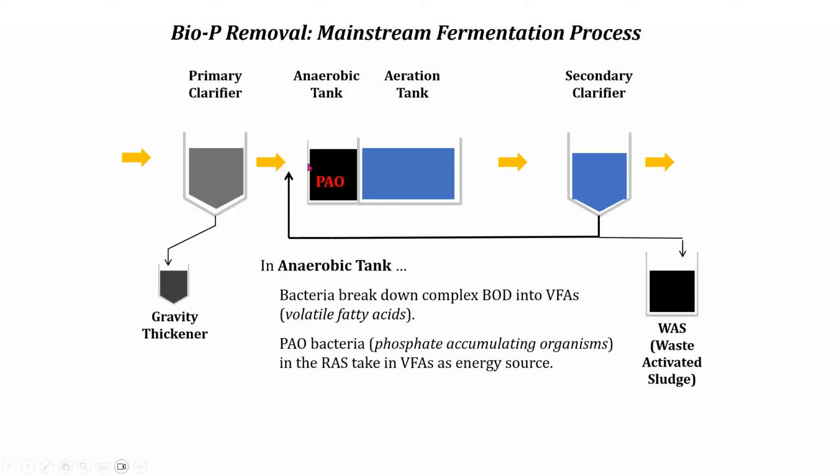So if you measure the phosphorus of the blend here, the soluble phosphorus, the orthophosphate, and you measure the soluble phosphorus leaving this, if it's about 3 to 1, then you know you've got the volatile fatty acids being produced, and the organisms that feed on them are there and are feeding on them and becoming energized. That would mean that this is a very viable environment.